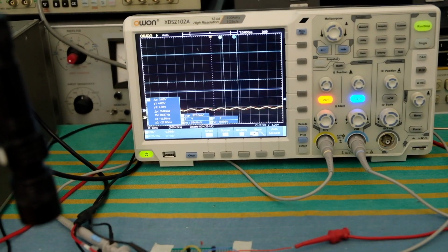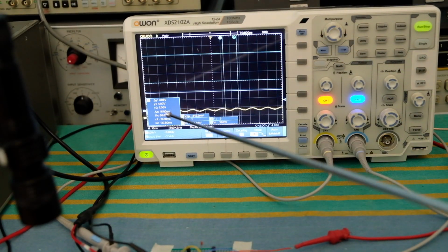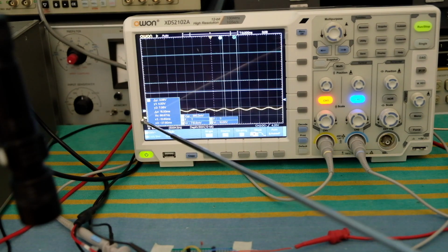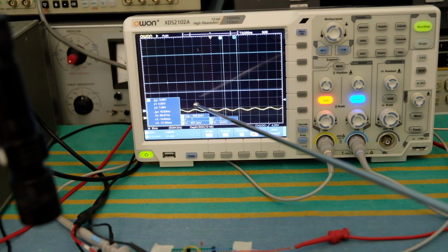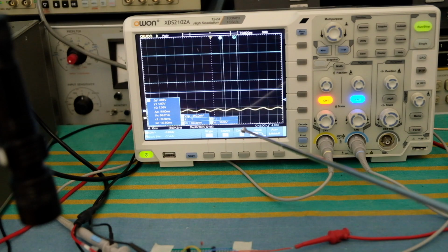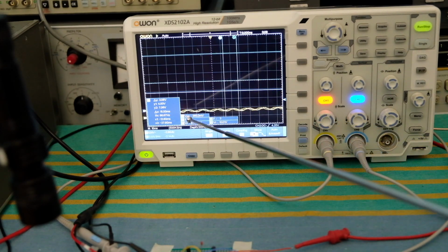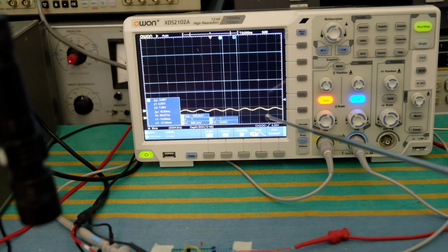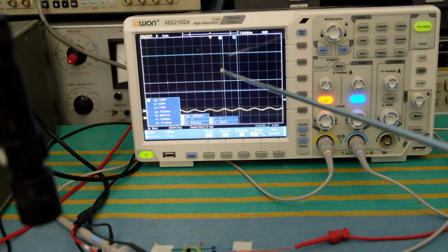This is the setup with the reset not being active, and you can see the output voltage is sitting very close to ground. The ground level is right here on the yellow curve, and it's got some ripple on this, basically some noise, or this room lighting has some 60 Hertz component in it, possibly affecting that. But it's almost down to zero because the capacitor is discharged, there are no resets going on, and so nothing to pull up the voltage to the supply, which is 10 volts.